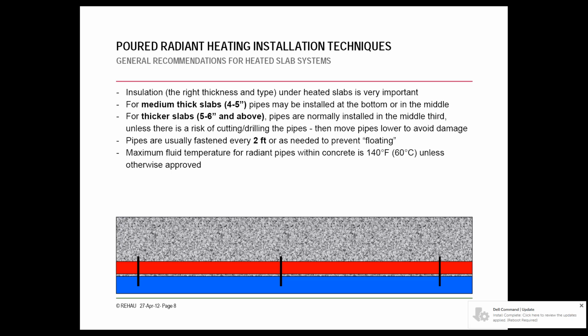It can be a foam underlayment, or a very common one would be an air-filled or bubble wrap type insulation that has a radiant barrier. Both of those are acceptable. The engineer in certain situations might specify one or the other at their discretion, and that's certainly up to them. We've used both in different situations and both work very well.